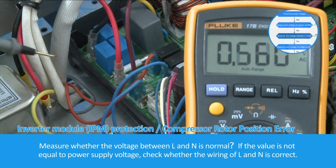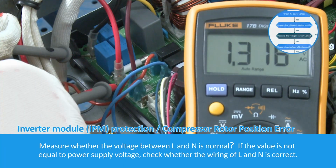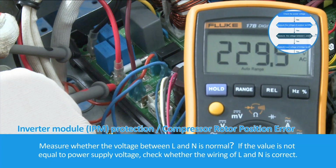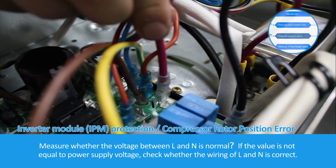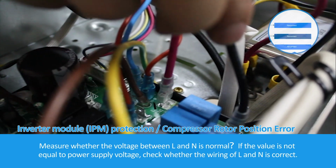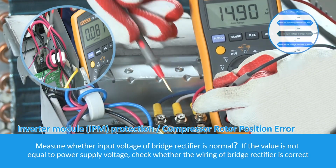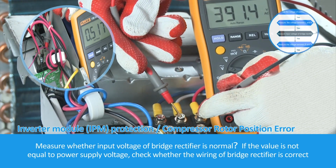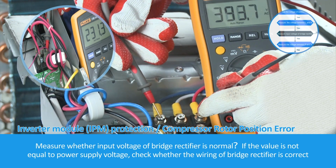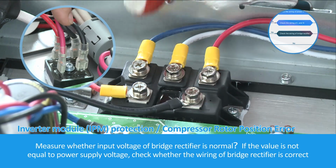Measure whether the voltage between L and N is normal. If the value is not equal to the power supply voltage, check whether the wiring of L and N is correct. Measure whether the input voltage of the bridge rectifier is normal. If the value is not equal to the power supply voltage, check whether the wiring of the bridge rectifier is correct.